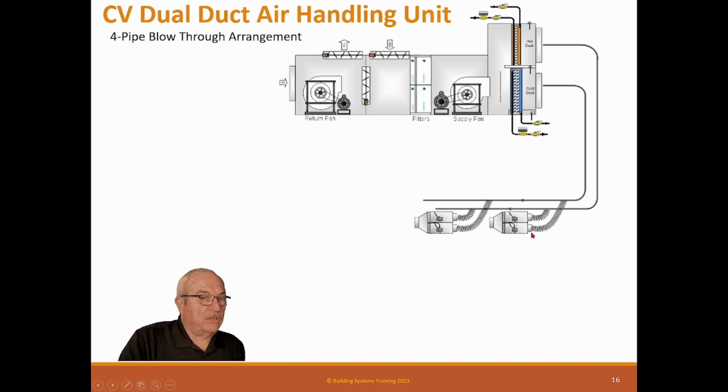Now, that's the good news. These work really, really well. The bad news, they're expensive because you're running two duct systems, and they're full flow duct systems because this one, it depends. If you were in a hot climate, this duct would be 100% of this air handler can flow down this duct. And maybe you never needed that much air for heating, so this would be a maybe slightly smaller duct. Or vice versa, the heating system, this would be full flow, and this may not be quite full flow duct system. Part of the design, but that's the way it does.